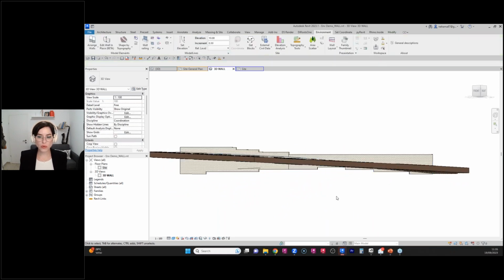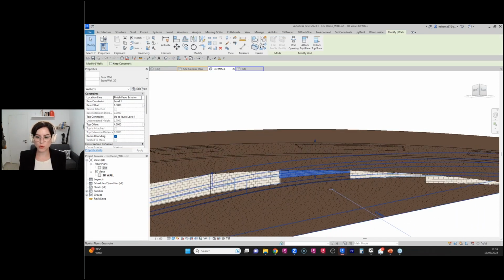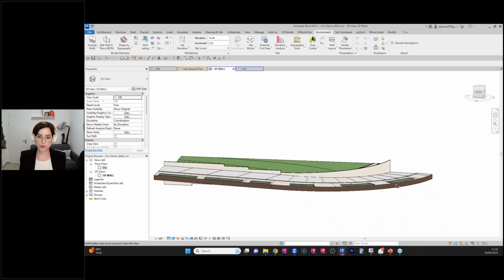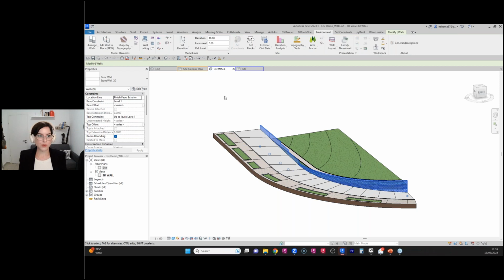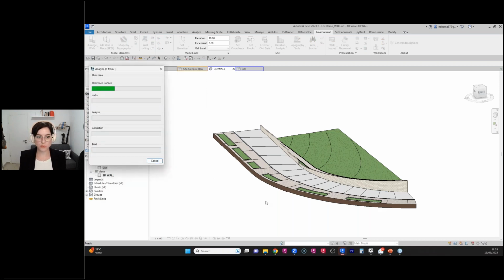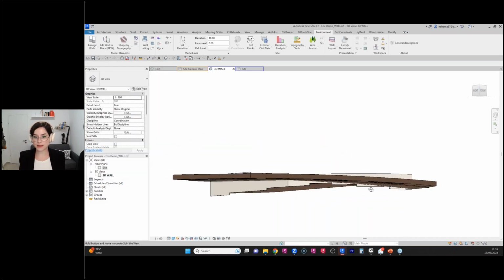So if you're already using Revit, you should know that everything you create with Environment is a native Revit element. That's just a Revit wall. So if you collaborate with other people who don't have Environment, it doesn't matter. They can always go back and edit their walls. I can always tab select this chain of walls and then go to the Arrange Wall option and maybe change one of the values and very, very quickly get an idea of a different design option, see what I like best.